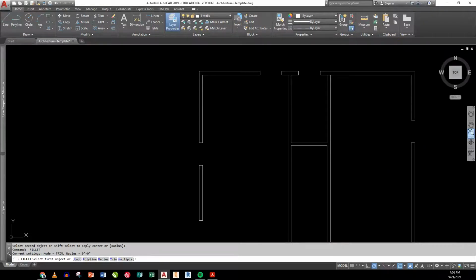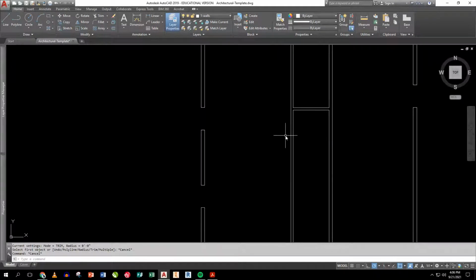Okay. Now next, I got to put in a laundry room. Well, the laundry room is 8'4" across, but that takes into the wall, so it's actually going to be rounded down. From inside edge to inside edge of that laundry room is actually 8 feet. Okay, so I'm literally just going to go like this. Go offset 96 inches from here down. Offset. Enter, enter. So I go out of the command and back into the command.